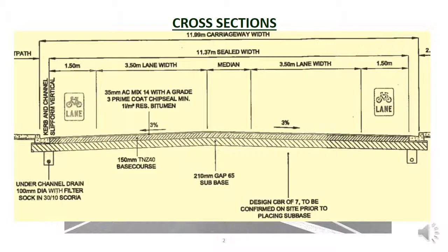The depth of the subbase and base course layers is also part of the design process. The subgrade and pavement supporting the road need to be designed to resist traffic loads. These loads are not just the weight of the vehicles, but also the lateral or horizontal forces from vehicles accelerating, turning, and braking.